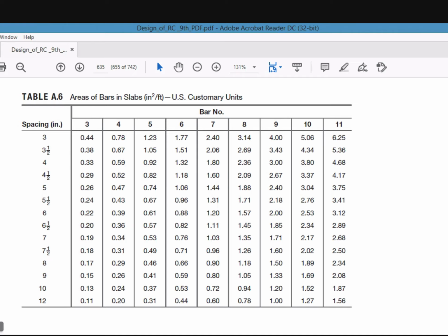See how easy it is? You just go to this table. Although we take 1 foot strip, we can calculate the area of steel per foot. That's what this is here, inches square per foot. This foot is that foot strip that we took. So if my area of steel is 0.24 in 1 foot strip, then my spacing has to be 10 inches on centers. Very important table and very easy to use. Any question before I flip the...